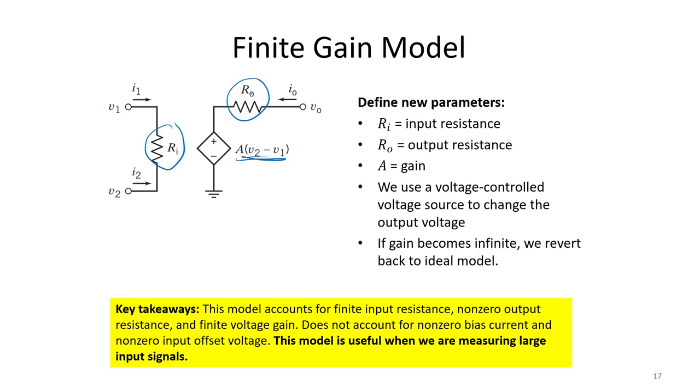So key takeaway, if you are measuring very large input signals on your operational amplifier, the finite gain model may become useful so that you don't end up with infinitely large gain that is beyond what is physically possible.